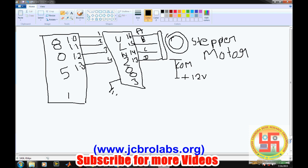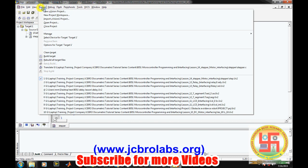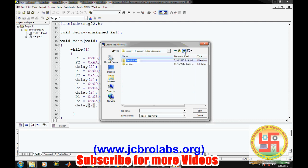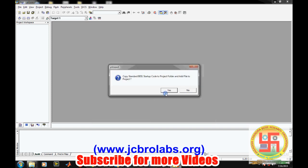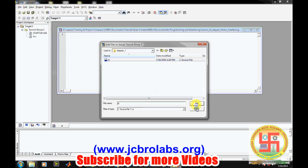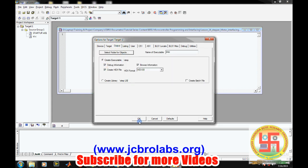Now let's write a program in embedded C on Keil in order to interface a stepper motor. Open Keil. Now create a new project, and let's select the 89S52 microcontroller, then save it with a .c extension, and add files to this group. Then go to manage options, which we have already done, and make the output create a hex file.